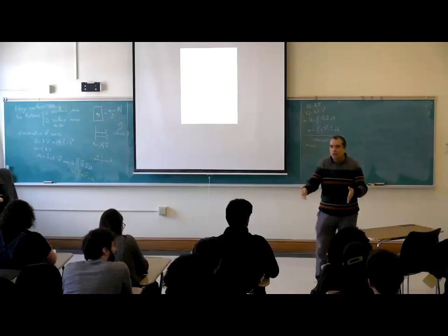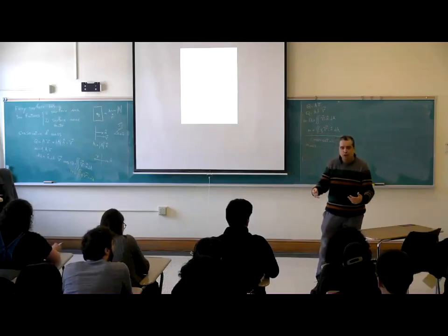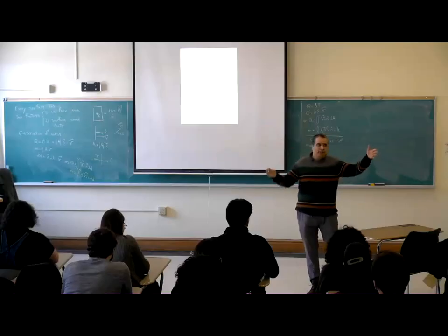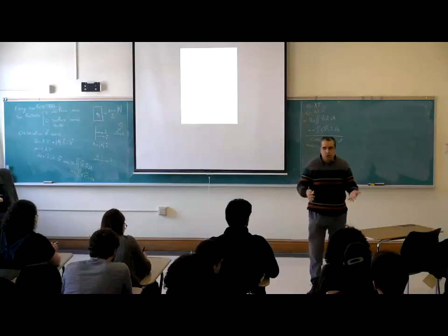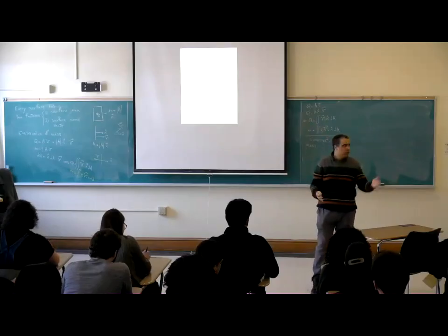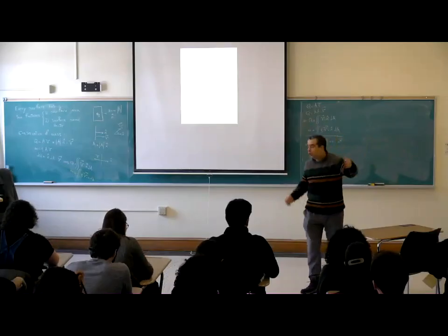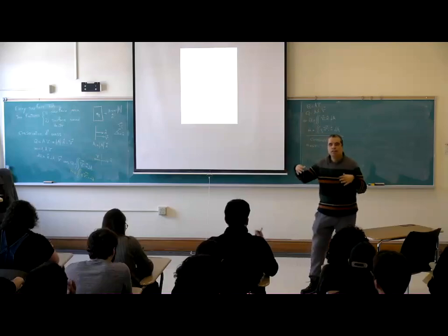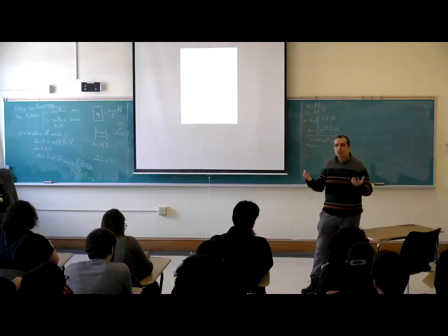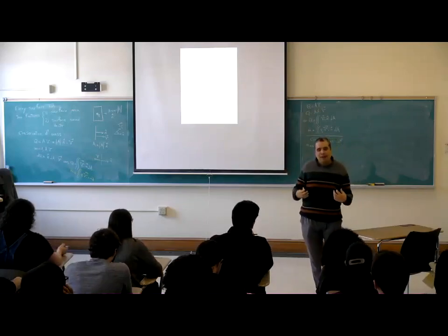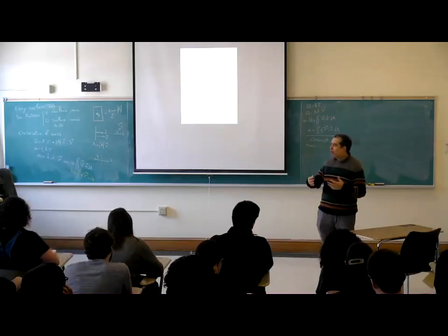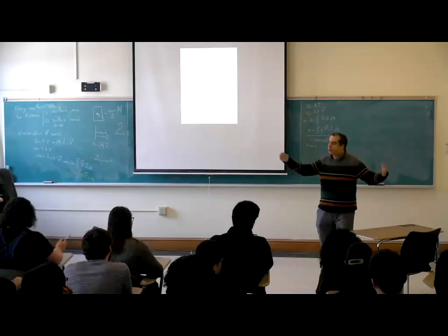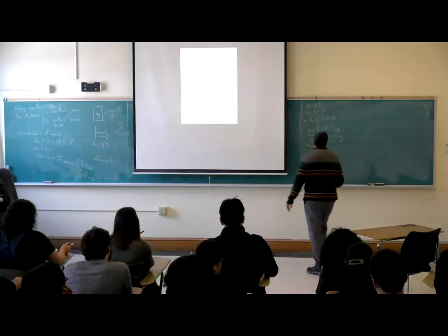The room is the control volume. The windows and door are the control surface. Control volume is the volume; two doors and a lot of windows are the control surface. So the rate of change of mass inside the control volume is equal to mass transport through the control surface.